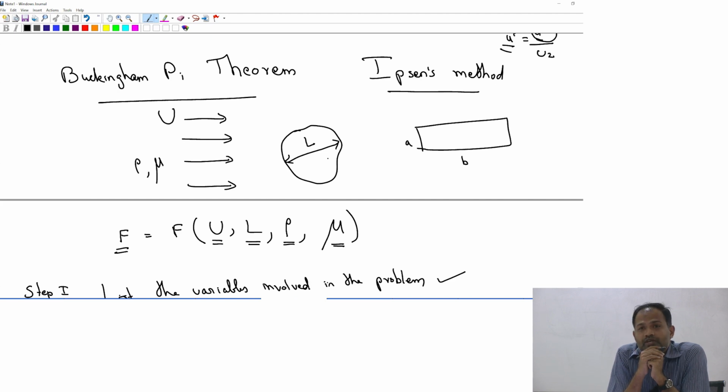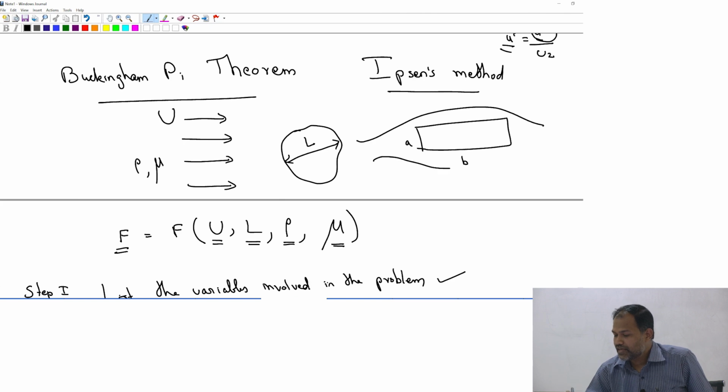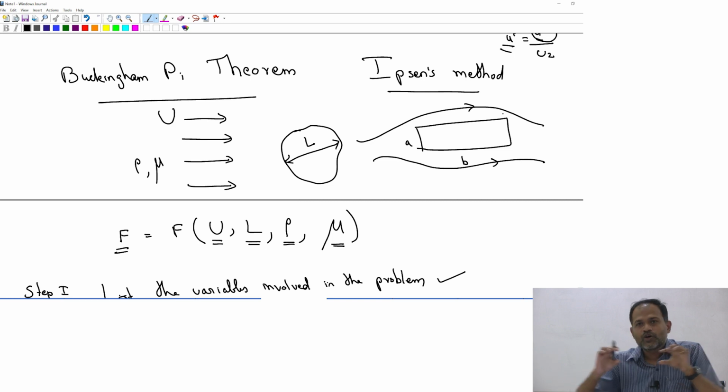How do you know B does not have any effect? See, fluid is going to go like that, right? So the regions of B, it's coming in contact a lot. There you are applying the no-slip boundary condition. The fluid is indeed going to go down, right? Whether it's a smaller one or whether it's a longer one, the fluid will slow down up to different extent.